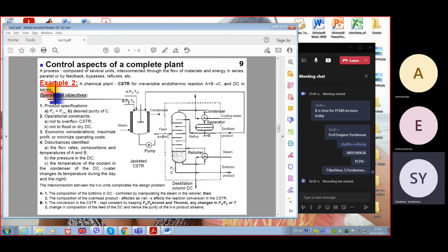The next again has a feeding flow rate and temperature. They are mixed inside. Steam maintains the desired temperature. The steam gives its heat to the inside components and is turned into condensate on leaving a sort of serpentine or jacket, because the steam is vapor, and here it is called steam, and that's why condensate.